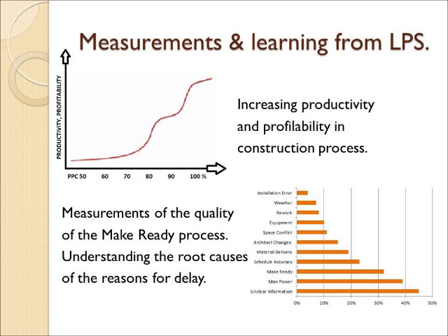After the Last Planner System is implemented, the measurements can be done. Each task not completed on time is highlighted and the problem is presented. Using graph methods, all the problems are put together to help understand the root causes of the delay. The reason for that is to understand the problem that caused the delay and to find a solution that will help prevent it in the future.